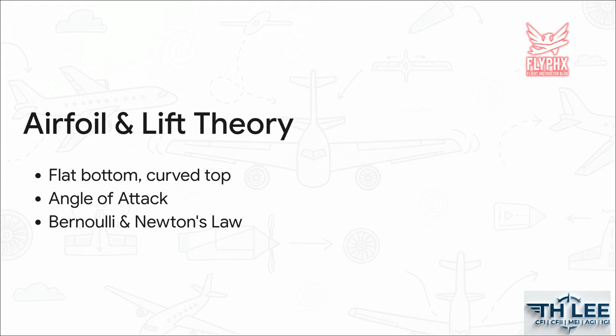Now, because air has viscosity, meaning it's slightly sticky, it tries to follow the curved shape of the wing in a smooth path called laminar airflow. Because the top is curved, the air speeds up, creating a low-pressure void right above the wing. Bernoulli's principle tells us that the higher pressure underneath will try to equalize, physically pushing the wing up into that void. Add in Newton's third law, where the wing forces massive amounts of air downwards as downwash, creating an equal and opposite reaction, and boom, you have lift.